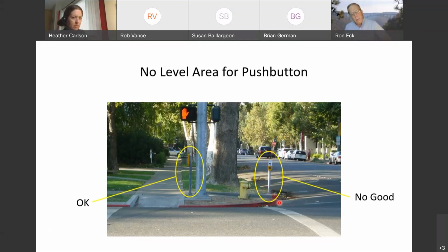Here in Morgantown, one of our main streets is 26%, the gradient of the street. And there's sidewalks adjacent to that street. Well, those sidewalks at 26% are acceptable in that case because they follow the street.